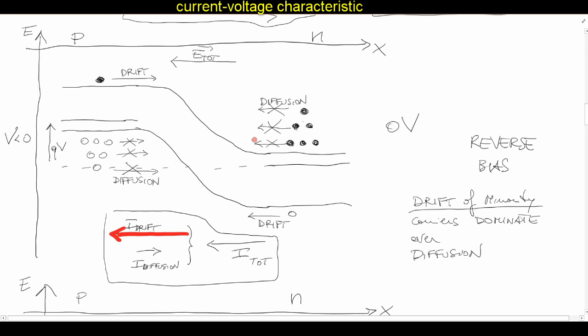At the same time, this could in principle diffuse. Oh, note, I didn't stress it previously. Diffusion is the other very important mechanism that we've seen. We did it in the semiconductors, we did also drift. The nice thing about diffusion is that carriers can diffuse in any direction. Here, they are going even against the external field applied. So diffusion is a very important process. Actually, for the PN junction it is fundamental. So in reverse bias, these cannot diffuse in that direction because there is a barrier they can't overcome.